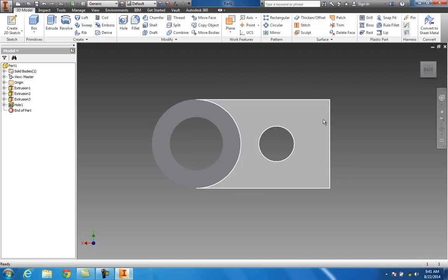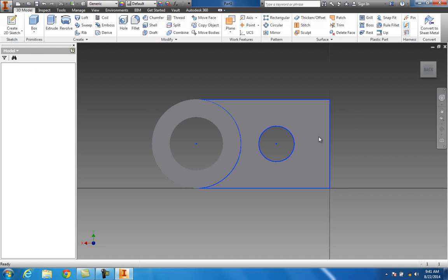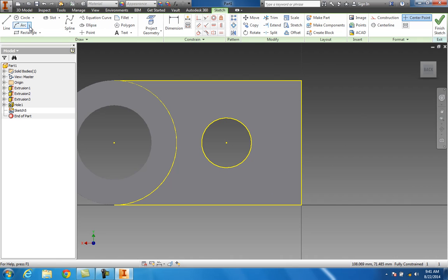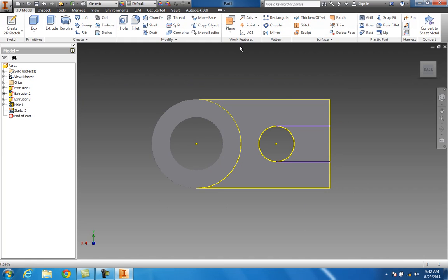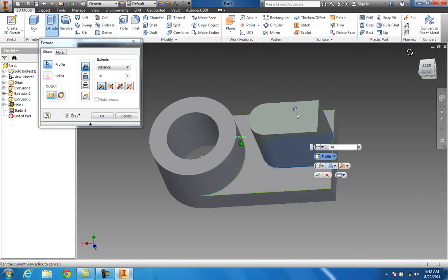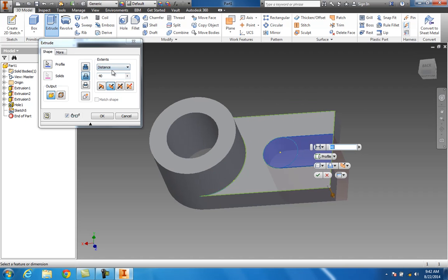I'm going to turn this thing around. I'll go back on the top of this, do a new sketch, and basically I'm going to cut the rest of this out the rest of the way. I'm just going to grab a line, come up here and catch that quadrant, bring it out there. Come over here, grab that quadrant, bring it straight out, and now let's finish that sketch. And I'm just going to hit extrude. All that. Make sure you use cut. And distance would be all.